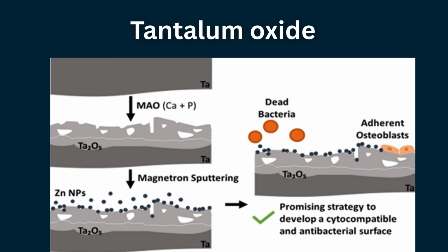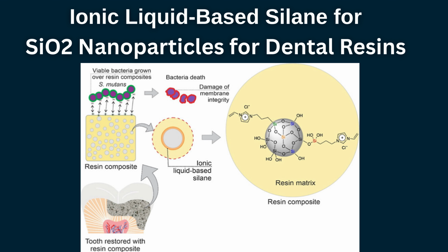Adhesives containing about 10 wt% tantalum oxide nanoparticles demonstrate improved resistance to hydrolytic degradation and enhanced microtensile bond strength. Silica. Silica is one of the most widely used fillers in dental materials. Incorporation of silica particles into dental adhesives improves mechanical strength, bond strength, and resistance to polymerization shrinkage.